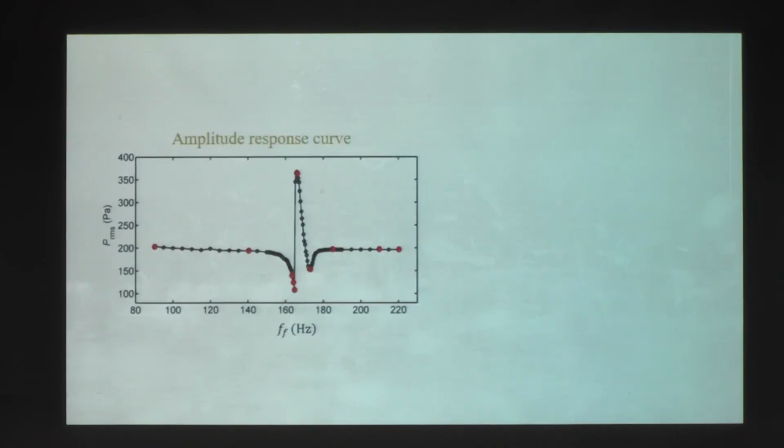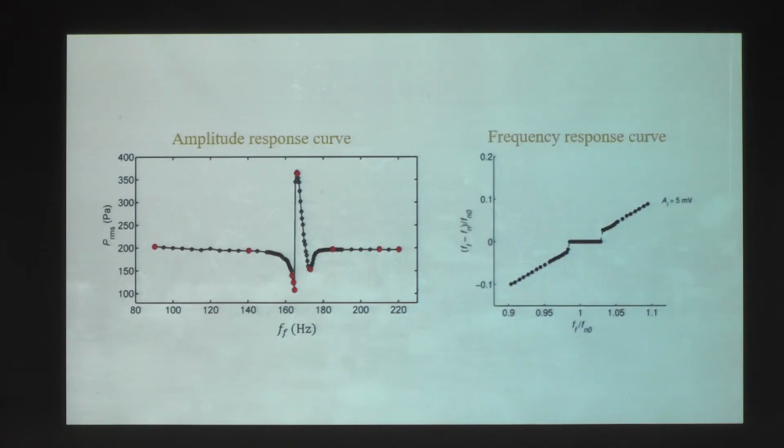Now, what is our objective actually? What will be the reduction, or whether there is any reduction at all in the final amplitude. We are calculating the p-rms of the response signal, and we see that when we sweep this forcing frequency, as we come closer to the synchronization boundary, the amplitude is reducing, but as soon as we enter the synchronization boundary, there is a high shoot up of the pressure oscillation.